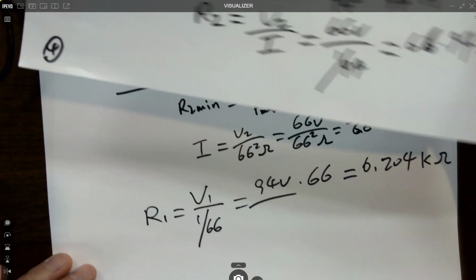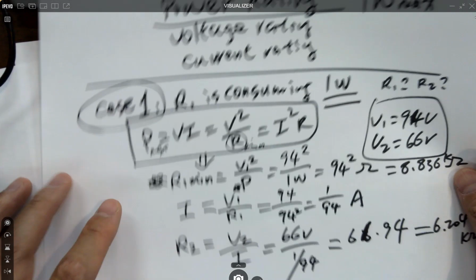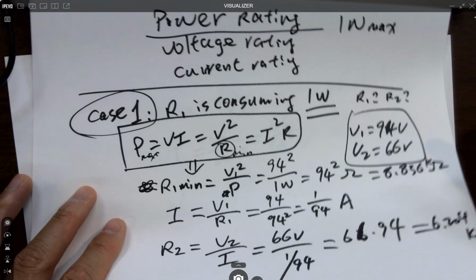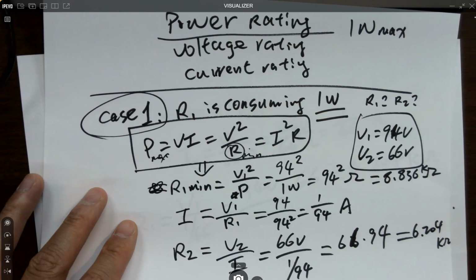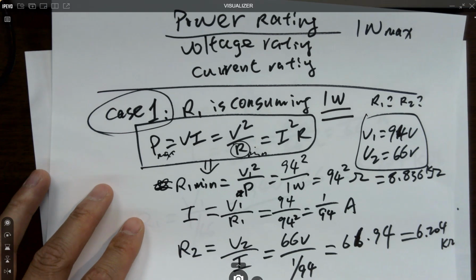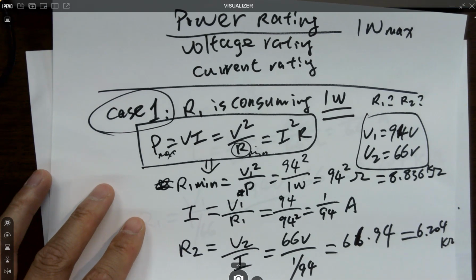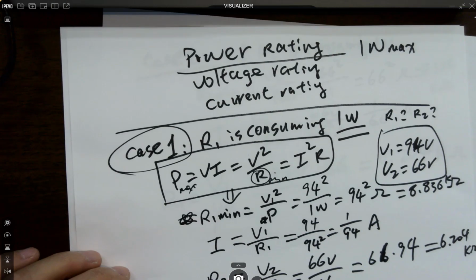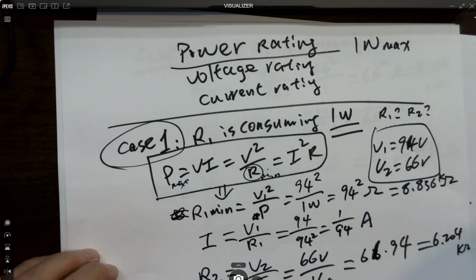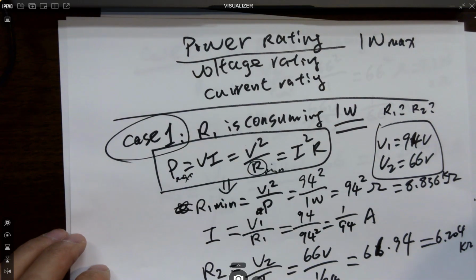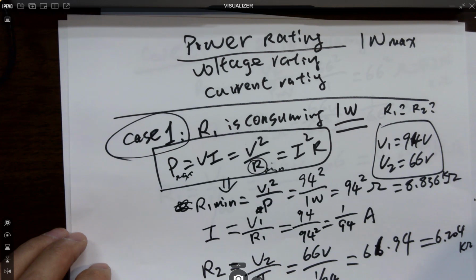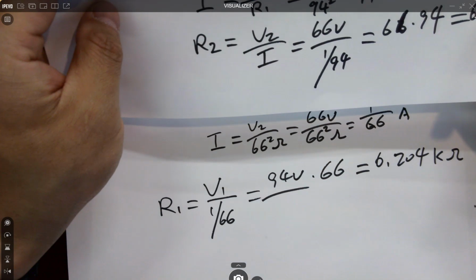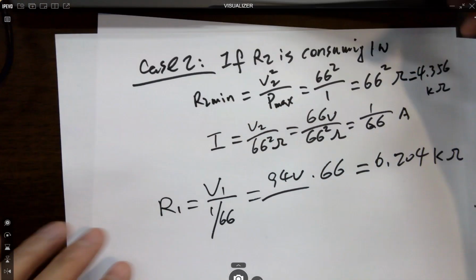But you know how to calculate the two sets of R values, right? So you can get one set here. You put in the solution. If the question was, if the maximum power is 1 watt, what is the greatest resistance those two can be? So shouldn't you just use the higher value? That would be right. Or what is the question actually asking? It's asking for the minimum R's to reach that 1 watt. Let's check it. See if anyone is over 1 watt, right? Yeah, so they cannot be over 1 watt.